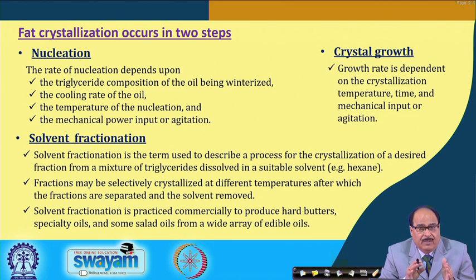The crystallization actually occurs in two steps. One is, as I told you, the nucleation and then the crystal growth. Rate of nucleation depends upon the triglyceride composition of the oil being winterized, the cooling rate of the oil, the temperature of the nucleation and the mechanical power input or agitation. The crystal growth depends upon the crystallization temperature, time and mechanical input or agitation.